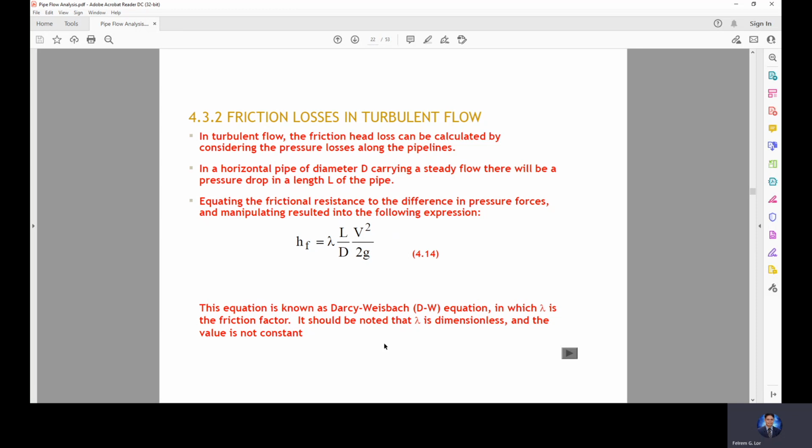It is an empirical way to determine the value of lambda, but in actual practice there are already tables given for different pipe materials, like PVC, GI pipes or plastic PPR pipe, with the corresponding friction factor value, so in problems it is usually given.